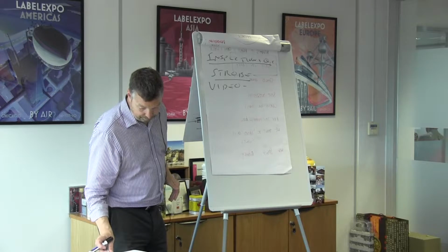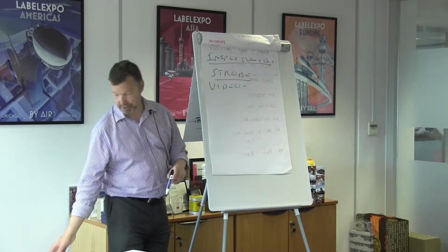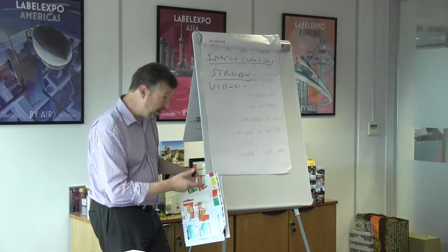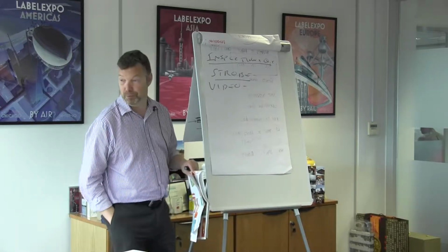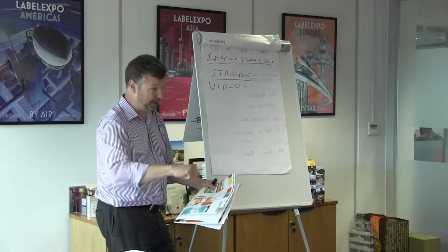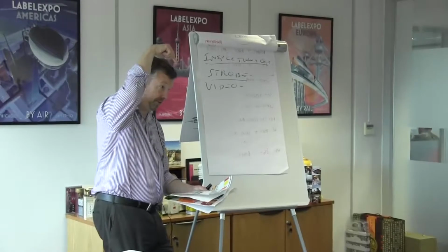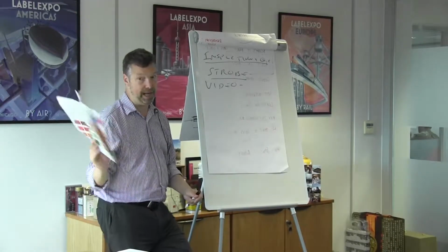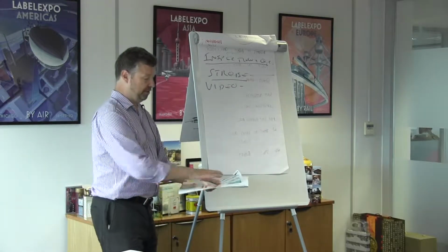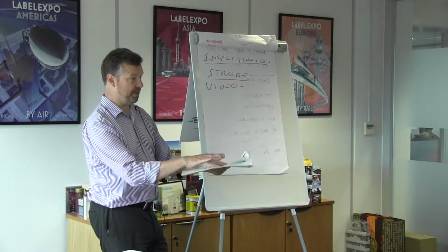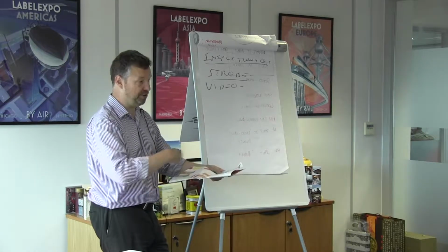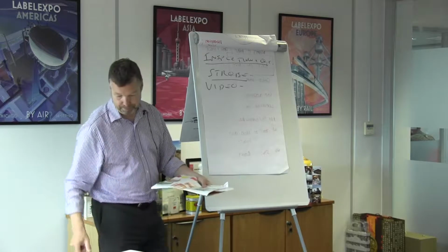So the video camera, the way that they basically work is, when you make ready the press, you've got your plates on, you start the press slowly, making sure that everything's lined up and nothing's falling off, all the image is correct. And just before you ramp the press up to full speed, the camera takes a photograph, bang, of the web. And that becomes what they call a golden image. What it then does is use that as a reference point for its inspection. As the web starts to ramp up to full speed, it uses that first image to check every other image that goes past.